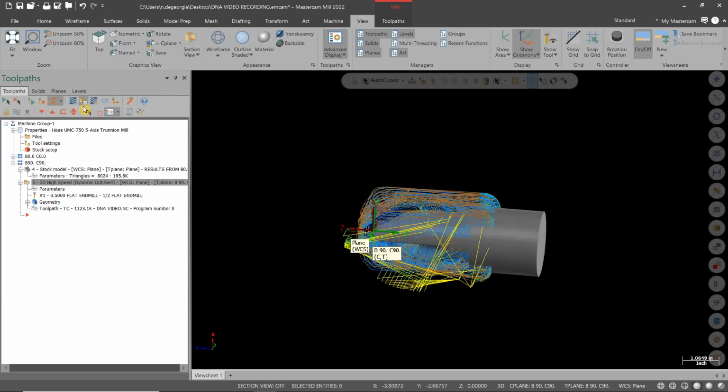Looking at this toolpath, I can see that some of the cutting marks go into the 2-inch diameter stock. To help this, I'm going to create a machining boundary, and this should clean this all up.